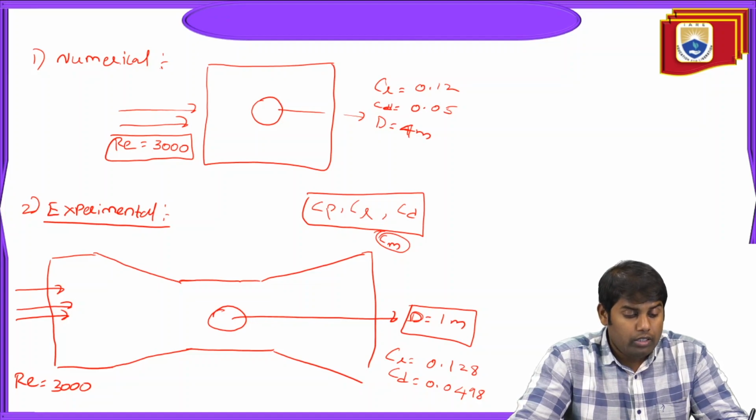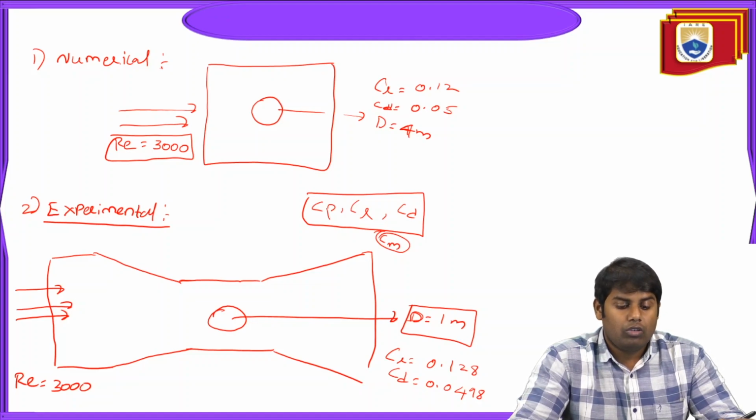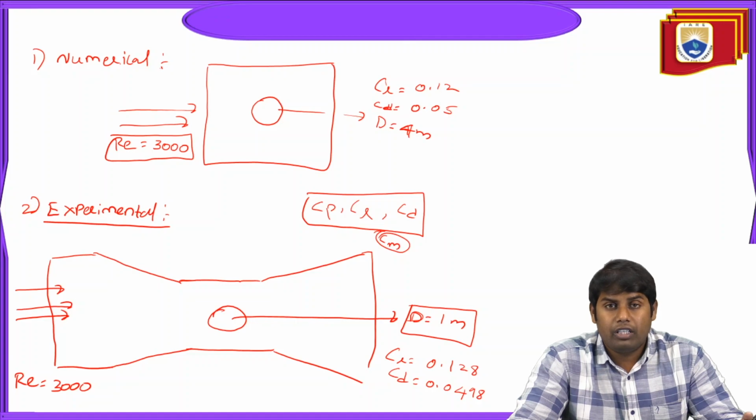Why? Because in the numerical case you have a computer aided simulated flow, where you actually simulate the turbulence level and the intensity of diffusivity and emissivity based on the key parameters which the simulation controls. Here you have the turbulent kinetic energy k, epsilon and omega.